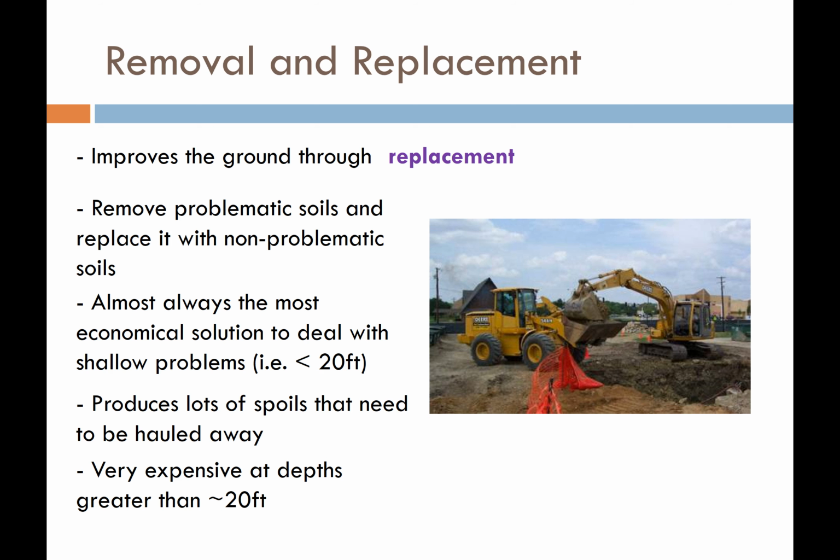Now, if you're going to try to do removal and replacement at deeper depths, depths greater than 20 feet, now we can be talking about expensive solutions because you have to use specialized equipment. It can be a problem. One of the things that we have to make sure of, when we're replacing the soil, is that we're not just dumping new sand loosely down into the hole.